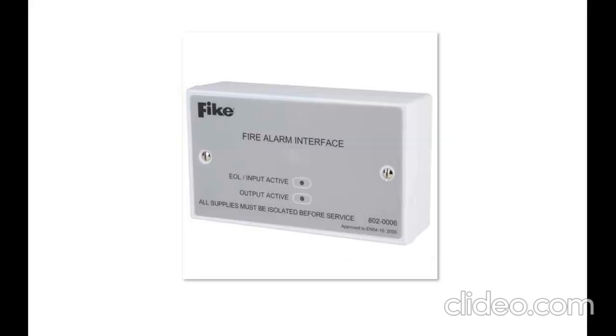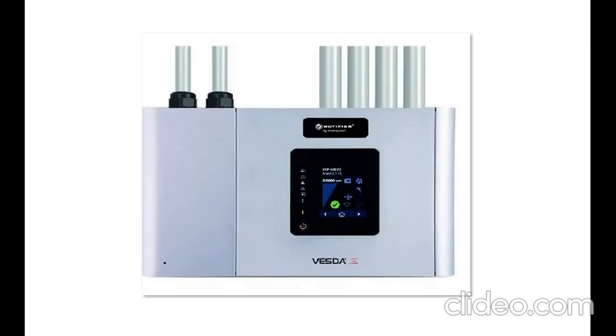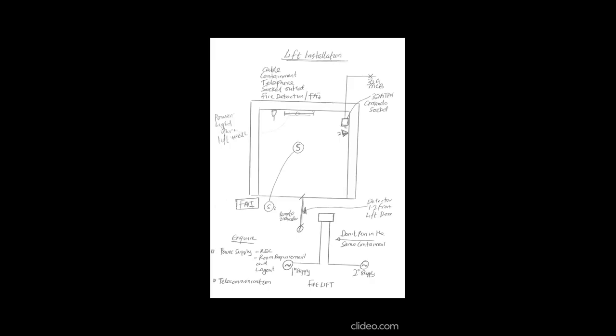Under the heat detector, heat detectors are used where smoke detection would generate a false alarm in the environment. Where the environment will cause a false alarm due to smoke, then heat detection is used. And there are two types of heat detectors. We have the rate of rise detectors and the fixed temperature.